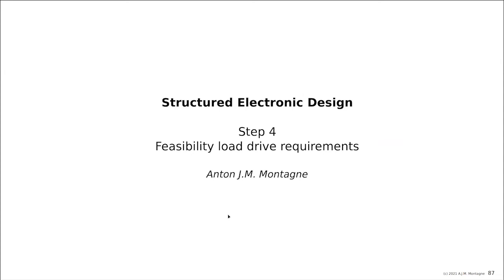So step 4 is an investigation of the load drive requirements. And this also is an aspect that cannot be improved by negative feedback. We can deteriorate it with negative feedback, because if we need to drive extra current into the feedback network, then we need to have devices that can drive more current, because the feedback network also needs current.